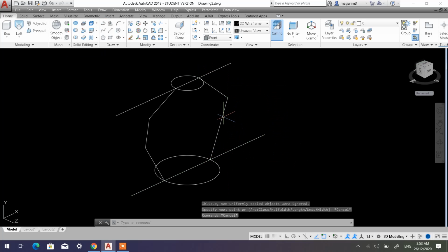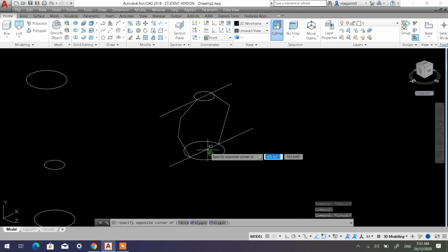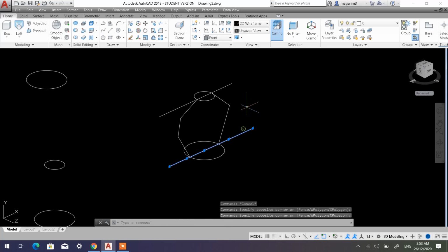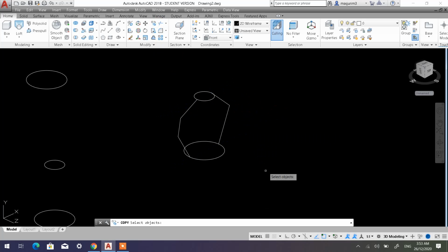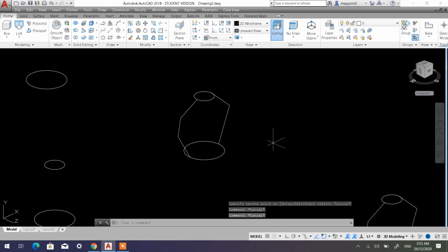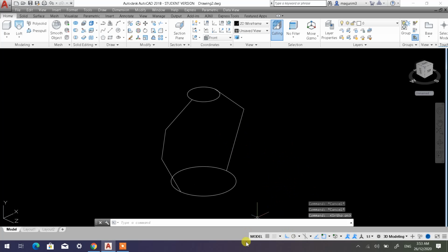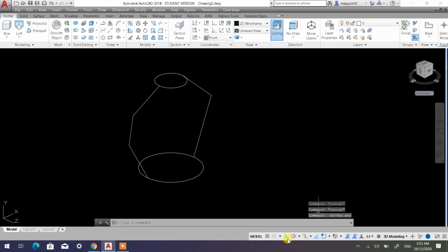Alright, so this polyline we don't need to join, because a polyline is already joined automatically for us. Once we have created this, we can simply delete all these guidelines. We don't want to use them. Let's say I copy this and put it aside first. Okay, now I'm going to turn my auto back on. If it's not on it's fine, just in case I turn auto on.